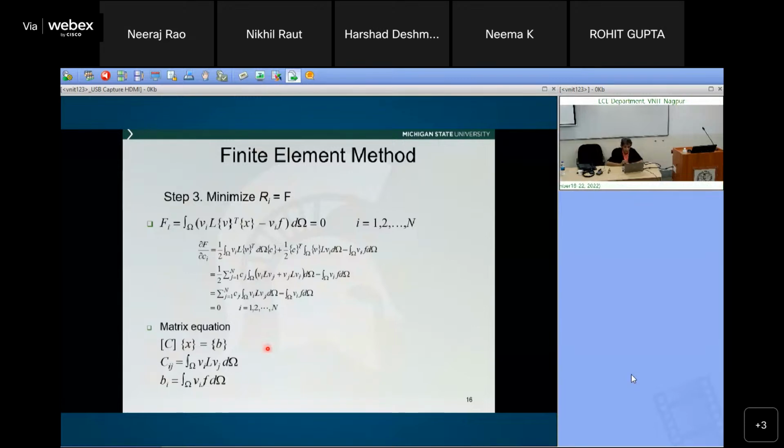See, in the case of static and quasi-static, like eddy current, it's a very local phenomenon. Even if you have 1 meter, I'm just going to model around the defect. That's all I'm going to model to look at the signal. If you have wave propagation, it's a different ball game, really. Those are different problems, and maybe an analytical or semi-analytical method is not what needs to be used. If you have a wave, if you're trying to model ultrasonic inspection or microwave inspection, it will be a slightly different problem.